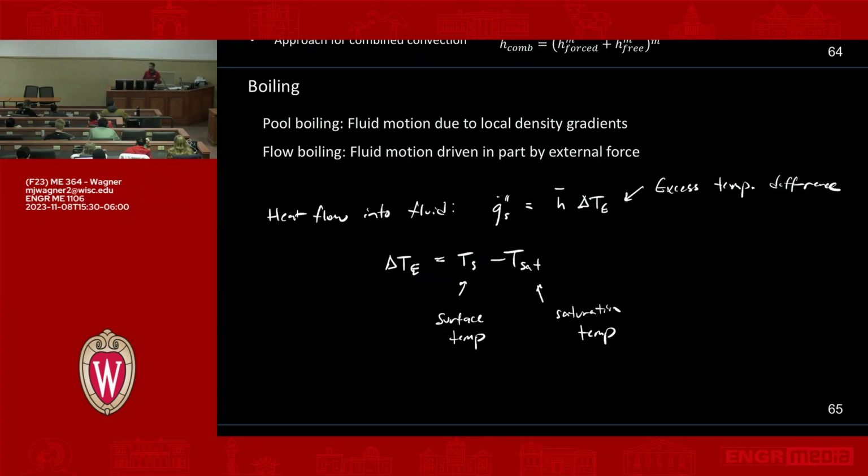So some things to maybe say about boiling. Typically, if you are constructing a boiler and you do it in a careful way where your boiling is what's called nucleate boiling, you don't really have to worry too much about the resistance due to boiling because it turns out phase change is a really, really good way of moving heat. So if you're boiling and it's in a certain regime, the heat transfer coefficient, this h, is so high that it is almost always negligible in your resistance network. Okay, but it's not always the case. If you start developing a layer of vapor, we'll talk about that next, then you can get into trouble. So typically boiling and condensation processes have really, really high h values, and so you can support, for a relatively small delta T, a really large heat flux, okay?